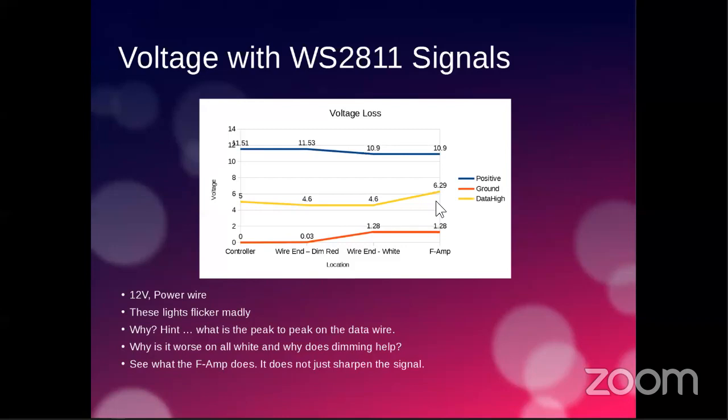What's the minimum positive you can run on a pixel? I see it at 10.9, but what's the minimum before it starts having issues? So it really varies in a couple of different ways. If this is true, why do 5-volt pixels never flicker? And they don't. Literally, you can run 5-volt pixels to the point where they're red to they're off and they will never flicker.